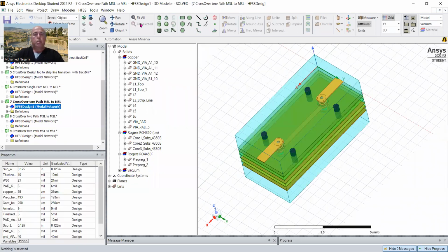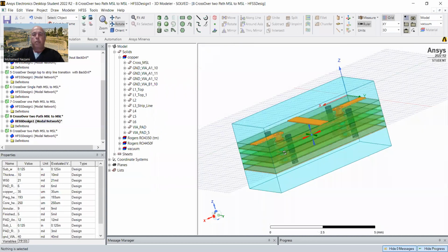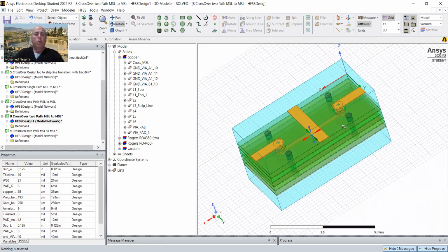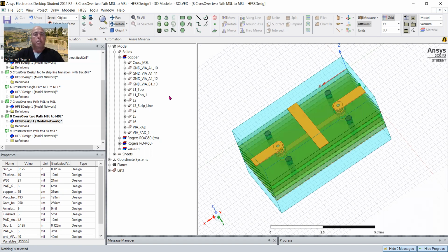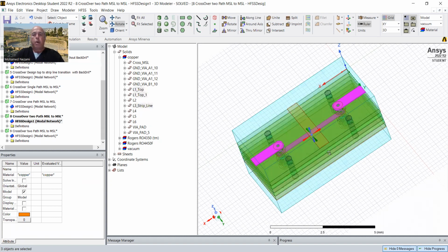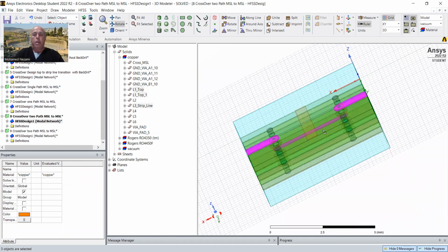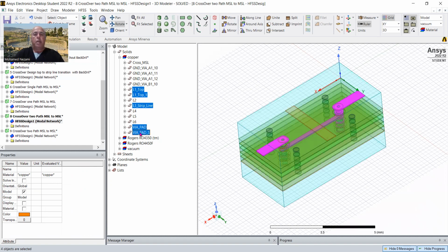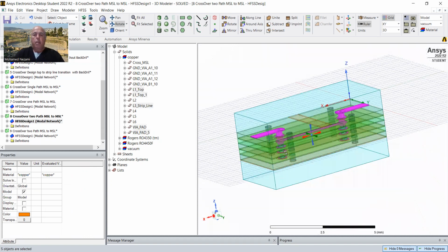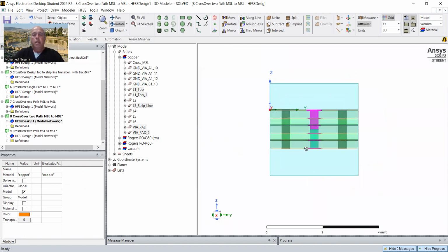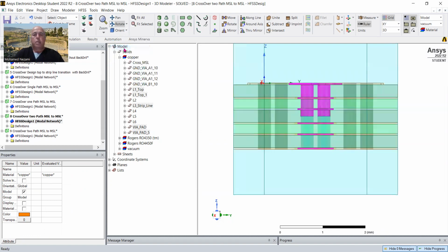What I need to do is, as you can see here, we have a microstrip line. This is a crossover that I'm designing right now, which we will go through. We have this microstrip line that comes in here, and there's another one that goes in here, and then in the bottom we have a strip line. You can see the strip line on layer 3, and then these are interconnected via 2 vias. So these 2 vias in this case here, as you can see, or let me look at these sideways.